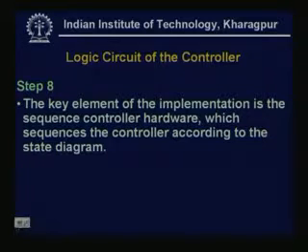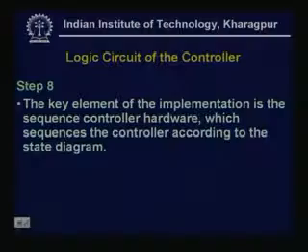The key element of the implementation is the sequence controller hardware, which sequences the controller according to the state diagram. We already drew the state diagram. We know what output should be generated, and what control signals will be high at what time state; that we have also derived. All the steps so far must be combined in this step 8 to get the actual logic circuit of the controller.